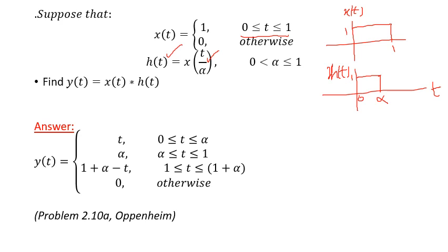So as you understand, we can reflect and shift any signal. So we reflect and shift the response signal, okay. So the resulting reflected and shifted version, okay. The second step, you understand that this is t, so you replace t by tau, so this will be x of tau, and this will be tau, and this will be h of tau.